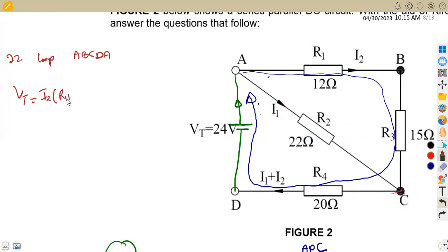So you're going to add R1 and R3 together. Plus, we still maintain the same direction from this point of C to the point A. We are maintaining the direction of current with I1 and I2 flowing now in this branch. This branch, we are now having another current, which is I1, I2, multiplied to R4. So it's going to be R4 into I1 plus I2, like that.